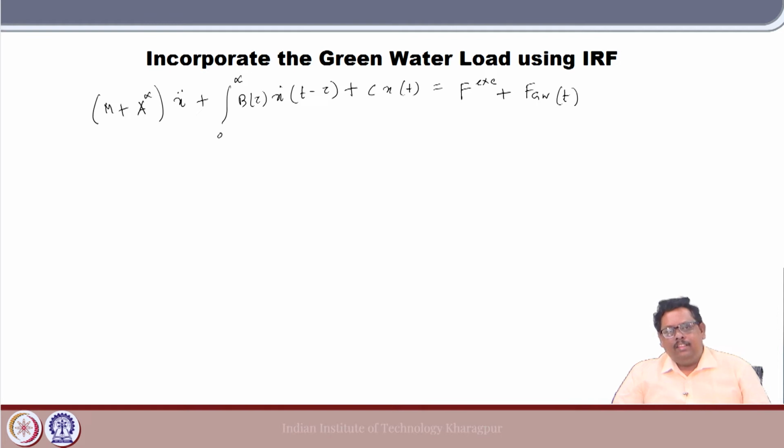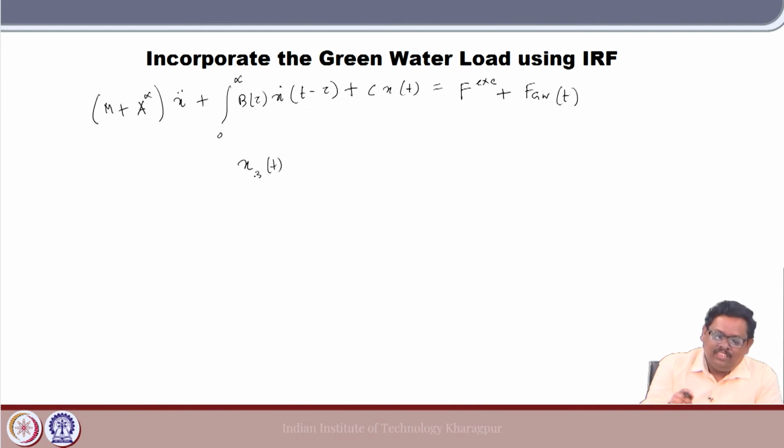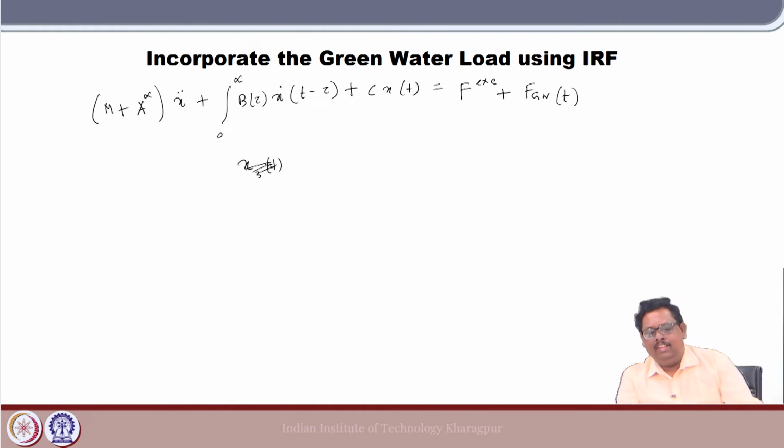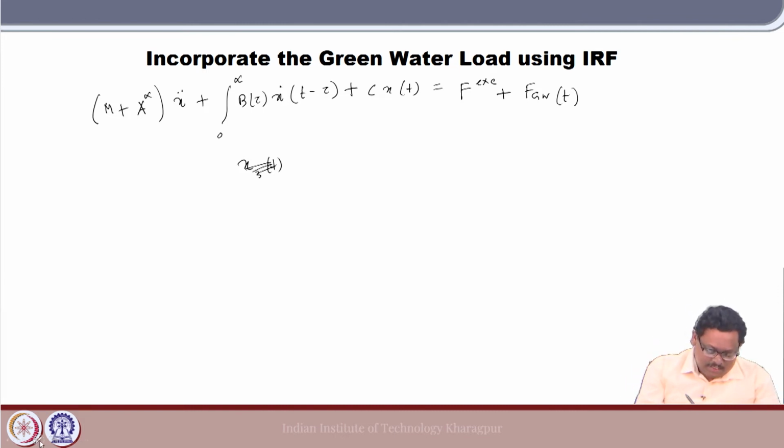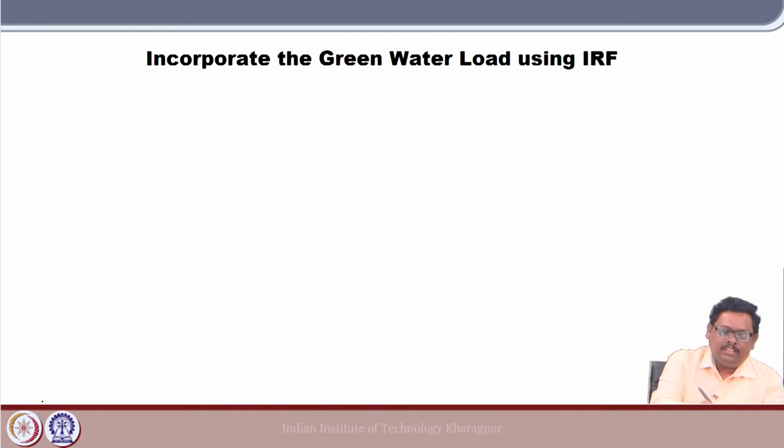Okay. Now, you know how to write the algorithm very well, right. So, here you will get the value for the heave. So, from here you could get the value for, let us say, x 3 t. Now, here x 5 equal to 0, so you cannot get the full benefit of it, of course. In order to get that, you have to incorporate the coupled equation also, right. So, I am just writing it. Suppose I want to solve heave and pitch coupling, then how could we do that? Okay, let me write it quickly and then we can move to the next topic.